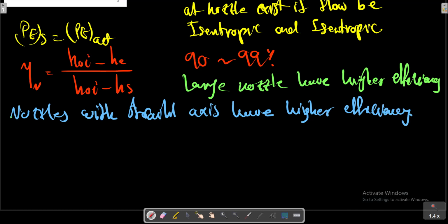The irreversibilities which cause the departure from isentropic flow are primarily due to frictional effects and are confined largely to the boundary layer. The rate of change of cross-section area along the nozzle is an important parameter in the design of an efficient nozzle, particularly the divergent section. Detailed consideration of this matter is beyond the scope of this text, and the reader is referred to a standard reference on the subject.